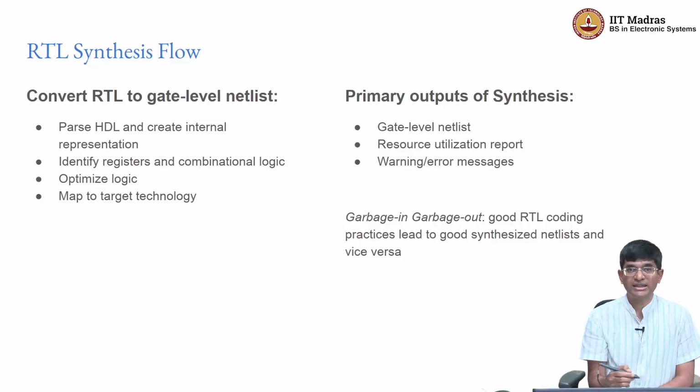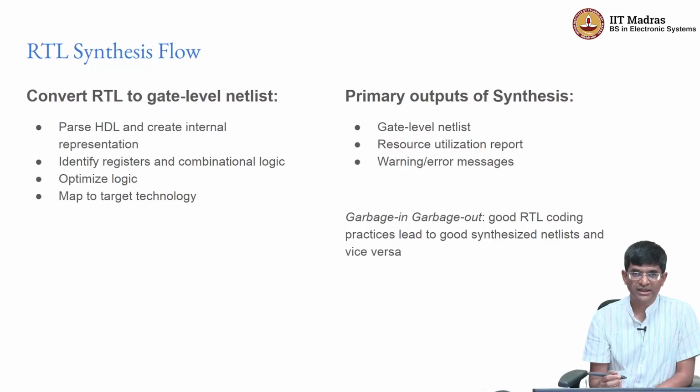So assuming that we have got a handle on how to write RTL, and of course the only way to really understand it is through examples, and we'll be working through many examples as part of the assignments, we now need to address another question. The RTL sounds alright, I have a mental picture of what my flip-flops and my logic look like, but do I actually need to create each one of those gates and put them down somewhere and connect them up, or is there some way by which magically all of this can come into place for me? And the answer is, that is where the synthesis flow comes in.